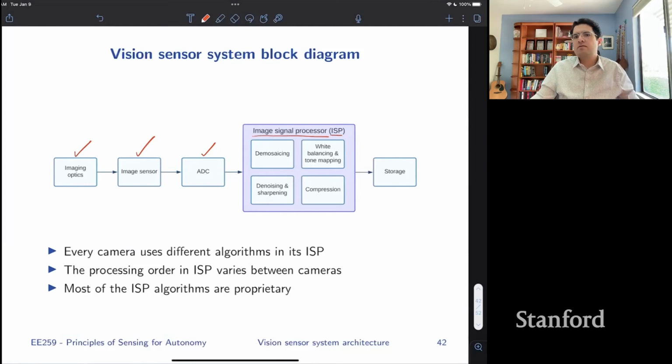Usually, cameras have a hardware module, a chip, that applies different signal processing steps to the digitized readouts of the sensor. The job of that is to convert the RGB mosaic that you get out of the sensor to a natural looking image.